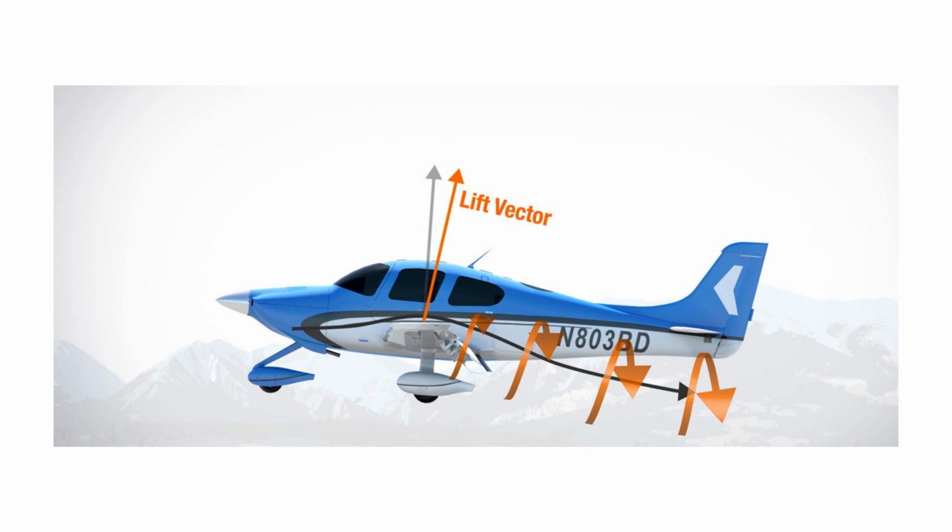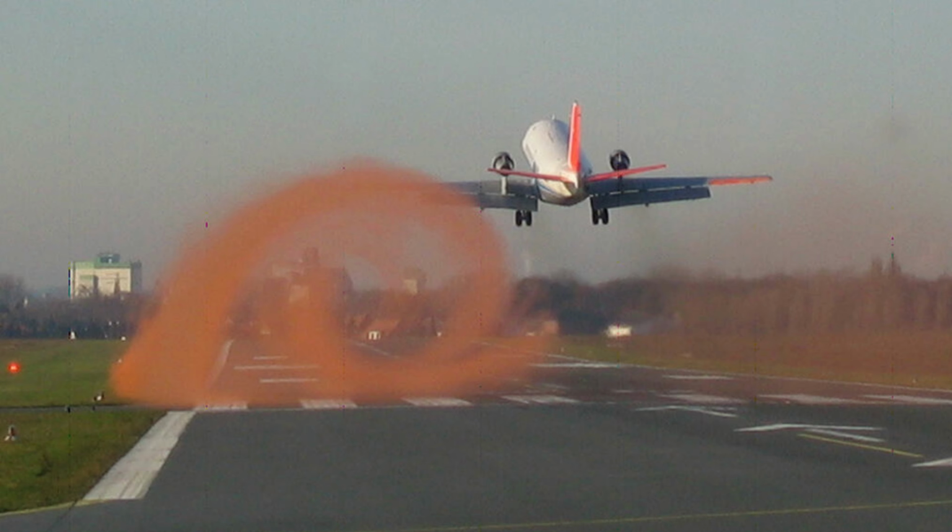Pilots need to know how vortices behave and dissipate so that they can predict their movement and avoid catching wake turbulence. The vortex movement changes when they're within a couple of hundred feet to the ground. If they're generated by a large aircraft flying at 1,000 or 2,000 feet, the vortices won't have deteriorated entirely by the time they sink to the ground. As the swirling air strikes the ground, the vortex is pushed laterally along the surface. Pilots need to keep this behavior in mind as they're likely to encounter these vortices while they're on approach or during departure. This lateral movement takes place at a speed of about 2 or 3 knots.